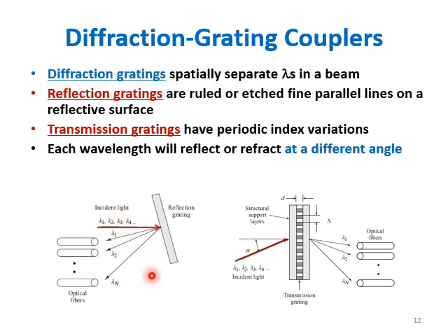Beams lambda 1 to lambda n, consisting of one single beam, hit the reflection grating and are reflected at different angles because of the different wavelengths. Lambda 1 emerges separately, lambda 2 at a different angle, lambda n at another, and each is then pushed into the optical fiber.